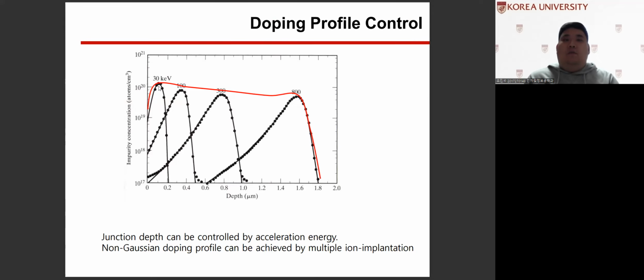As I have told you before, the amount of energy we give the ion can vary the depth of the ion implantation. So if we use techniques such as varying the energy and implanting with multiple ion beams, we can make the ion implantation profile even better.